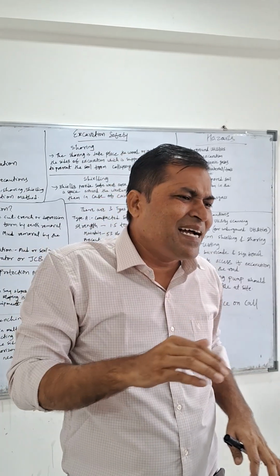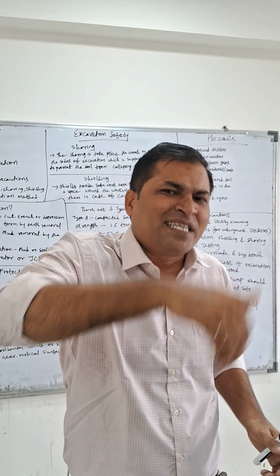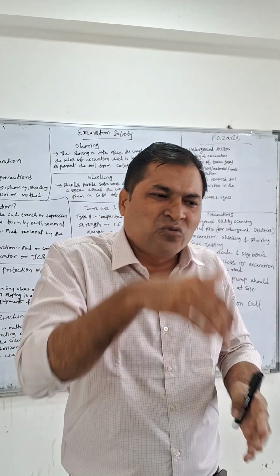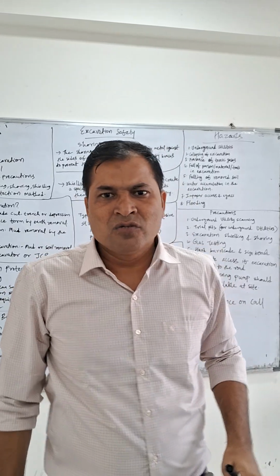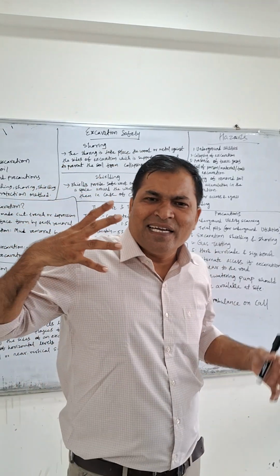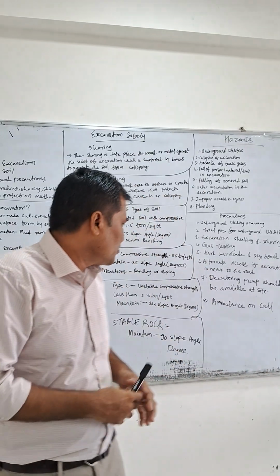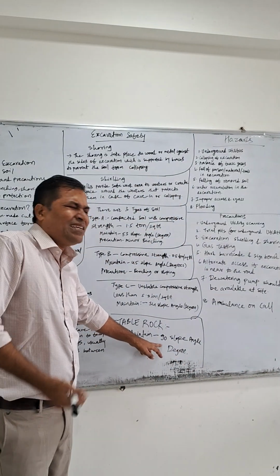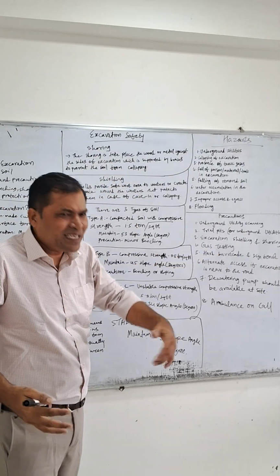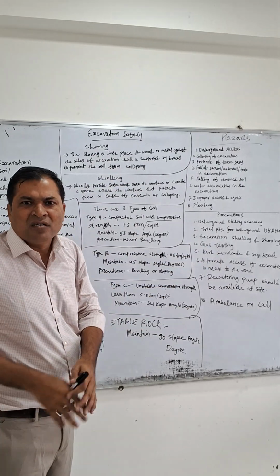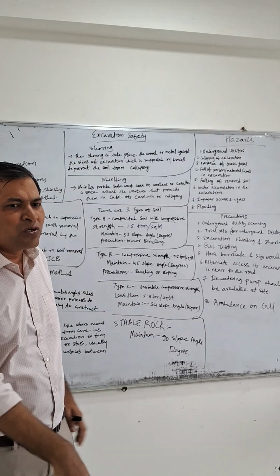So in that area, it is not possible to go with manual digging. Always you have to use an excavator. You need to cut that stone, remove that stone. It will be a heavy process. So you need advanced machines to excavate that point. In that kind of excavation, you can go with a 90-degree slope. Why? Because in rocky fields, nothing can go inside. Totally covered with rock only. So you can make a 90-degree slope. You can put the ladder.